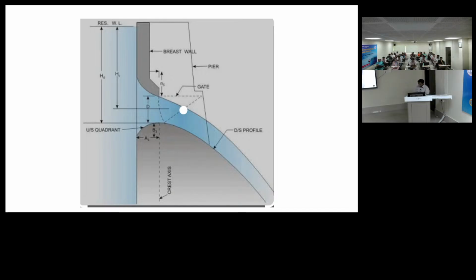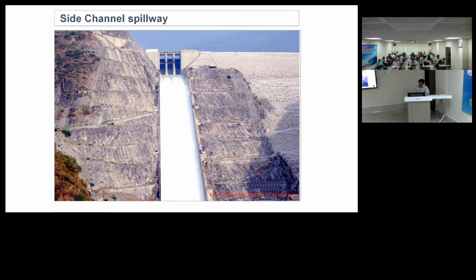So this is a sluice spillway; you can also call it an orifice spillway. Then one more spillway, the side channel spillway, which is just like an Ogee spillway, but like I told, in earthen dams, if the width of the valley is very narrow, you cannot have both the spillway and the dam, right? So that's why they will have the spillway separately at the end of the abutments, or in some projects it will be completely in a separate place.